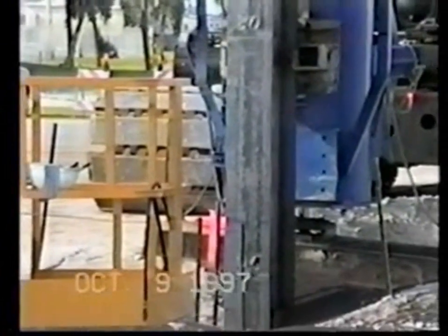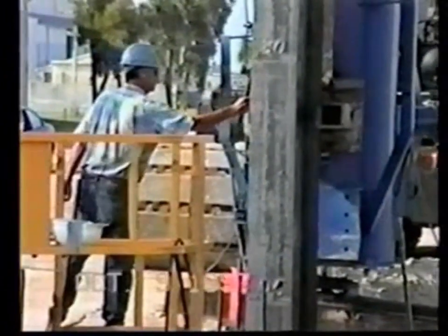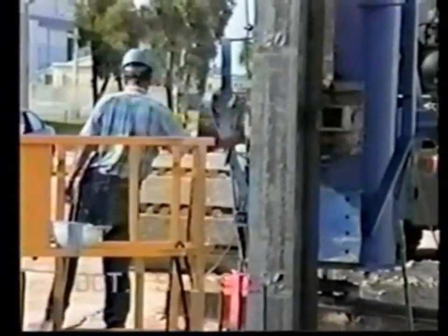Once both 1.5-ton bags of iron were in the mandrel, which filled it up to the bottom of the chute, the mandrel was vibrated out while testing the hollowness of the tubes. This was done by pounding on the external surface. The iron wall was filled to the surface to allow visual confirmation of wall continuity. The entire sequence for one probe, from start to finish, takes between 45 minutes and 1 hour.